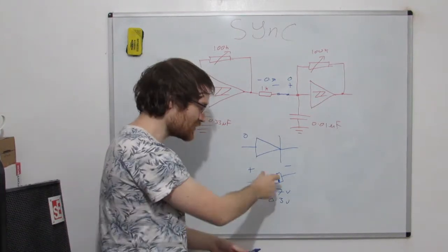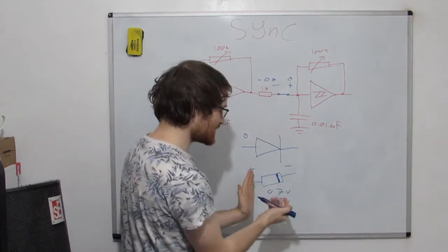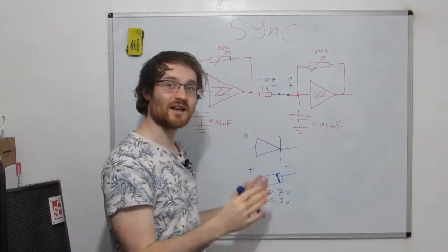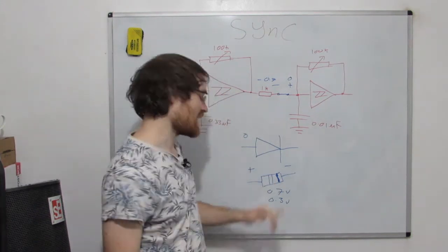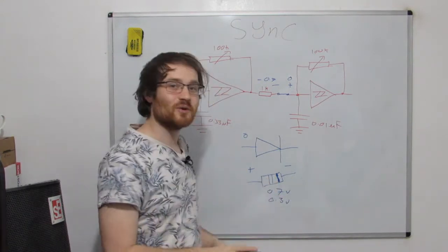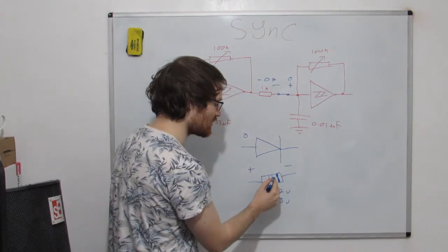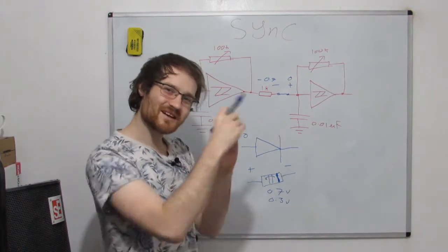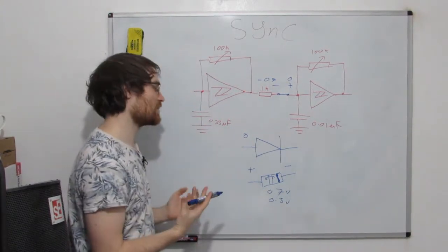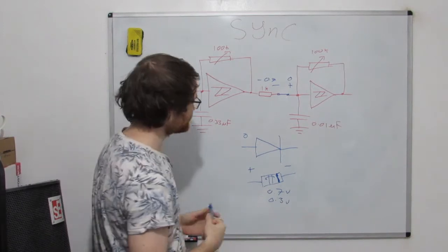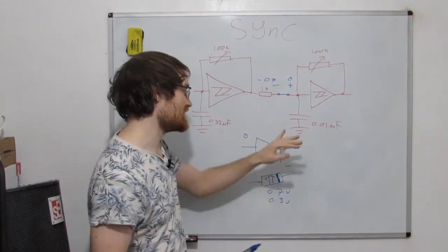It's a little chemical thing going on in here. There are electrons moving around and widening a little. There's a depletion layer in here where there's no electrons, basically. So you can imagine there's a little hole in the middle of here, and it acts like an insulator, but there will be a voltage where that doesn't matter. That gap isn't wide enough to stop the voltage jumping over, like you can imagine it arcing over. I'm trying to describe it without going too much into the physics of it, because it is a little bit complicated, and it doesn't matter. That'll be on the data sheet, it'll be rated at that.